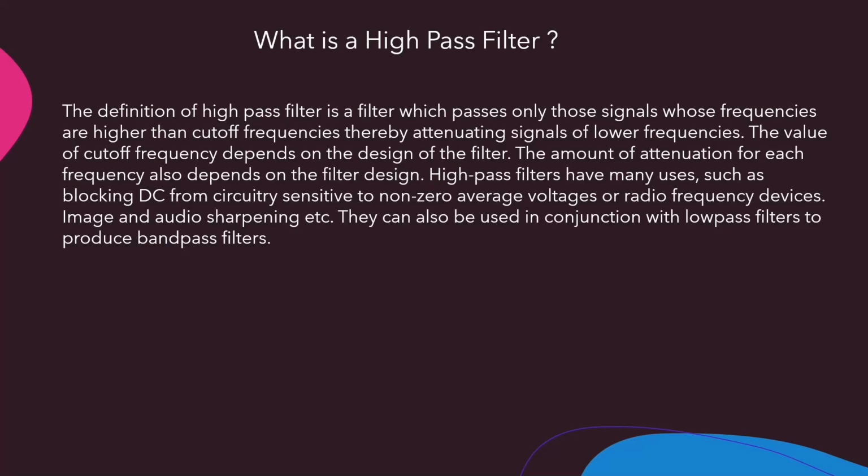High-pass filters have many uses, such as blocking DC from circuitry sensitive to non-zero average voltages or radio frequency devices. Image and audio sharpening also use high-pass filters. They can also be used in conjunction with low-pass filters to produce band-pass filters.